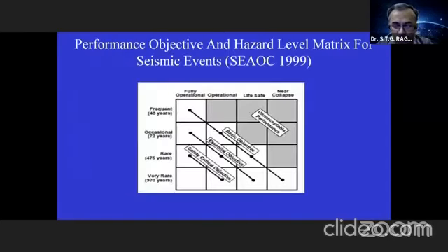And most of you know that performance-based design is very popular nowadays. If you want to design a structure as per performance-based design, they don't want one Z value. They want four Z values. They want a Z value for frequent, then occasional, then rare, and then very rare. And these are defined in terms of return periods like 43 years, 72 years, 475 years, and 970 years.